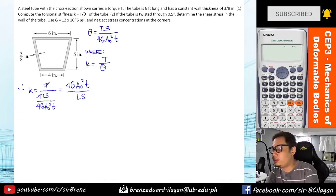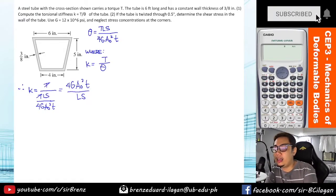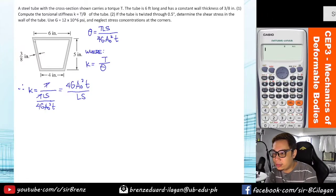Okay, so since we now know the formula to solve for the torsional stiffness, considering the given values, let's now solve for the area enclosed by the median line. As you can see in the figure, the 6 inches measurement was taken at the middle, at the midpoint. It's not from end to end. So I think we won't have any problem.